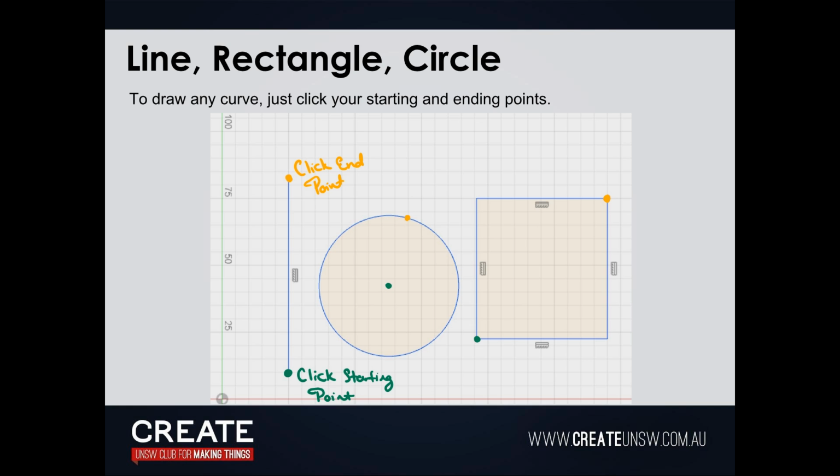Your sketches will be on the side here. I've deleted all the sketches, but they still exist. So for example, sketch 1 and 2 are already gone, but if you hover over it, it will highlight what sketch you are in. So right now this is the third sketch. Now if I want to hide that sketch, you just click the little light bulb on that, and it doesn't exist anymore. Well, it still exists, you just can't see it. Click back on the light bulb, it's there again.